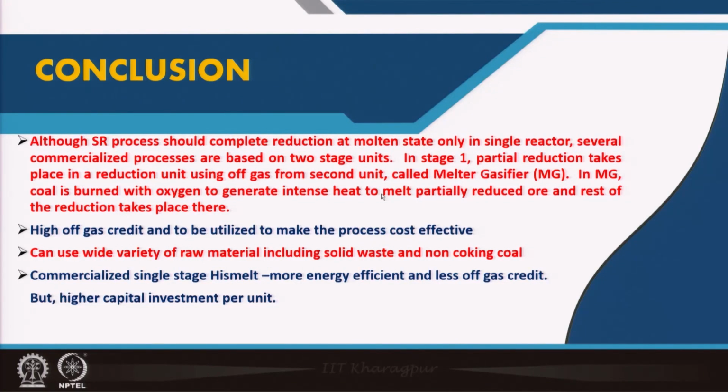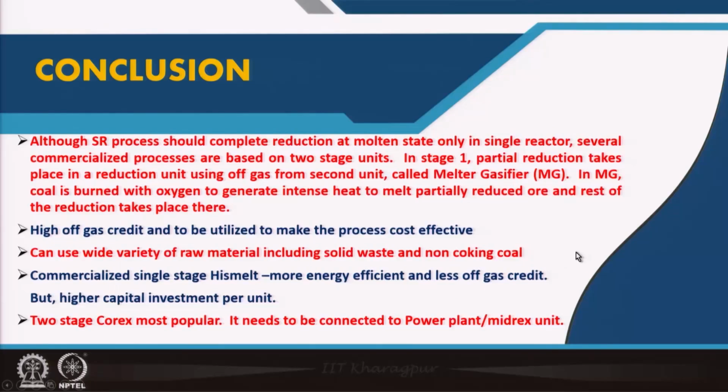The Finex process can be used for treating very low grade ore, and also the waste from the steel plant and all these things. Okay, so all these processes have very good potential to grow in future, and in India also we have the Corex process, and in future hopefully we will get the Hismelt type of process. Okay, thank you very much.